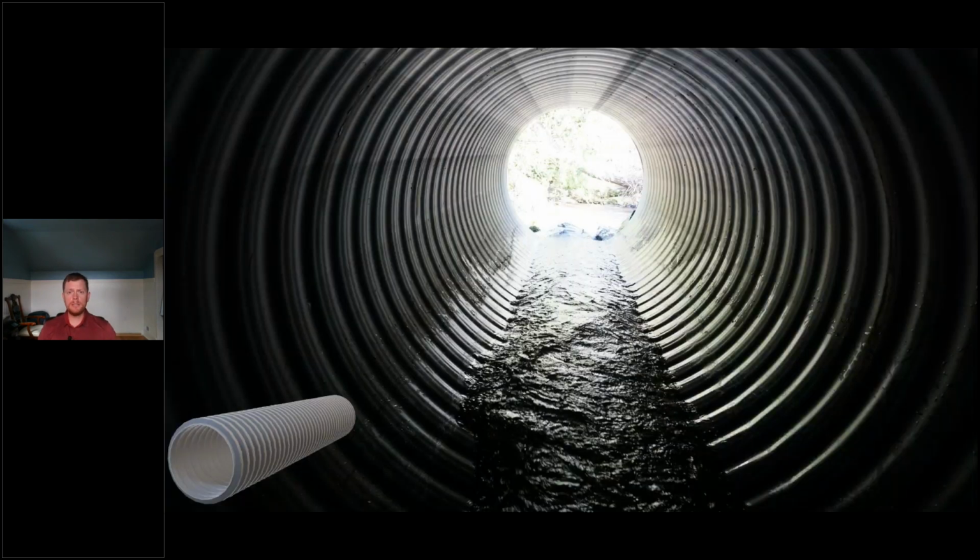All right. So now let's look at a plastic pipe example. This is a piece of polypropylene. This is a 48-inch pipe. It's the same diameter actually as the CMP we just looked at. You'll see a lot of similarities, with the exception of the rust, between the inside bore of this pipe. This is a triple wall pipe. It's installed a few miles from my house. It's got a couple feet of cover and an ADT of less than 500, I would assume.